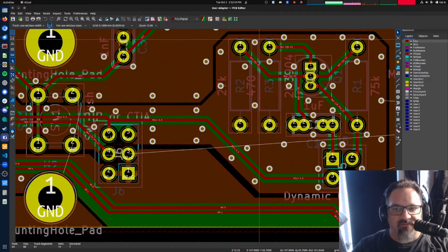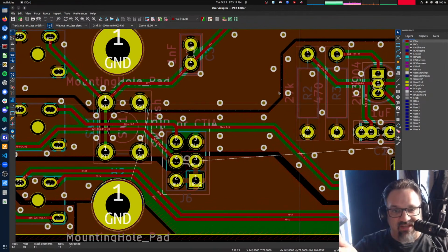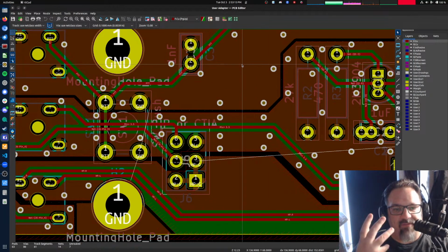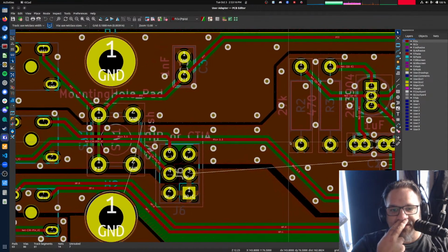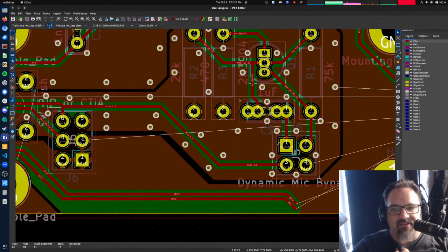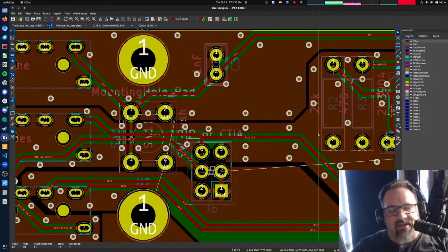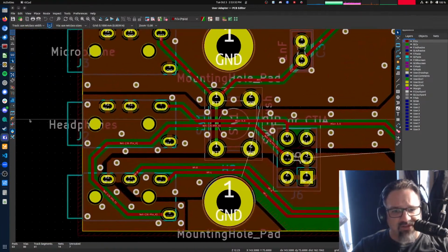So all of this here is mic ground or mic minus. I guess those are the only two places that have it. But by making the ground pour around all of this circuit, it makes it all reference to that ground. It should be the same, voltage-wise, as this ground, but I like keeping the currents isolated so that the return current from the PTT isn't going underneath this circuit, because then any noise that gets picked up in the PTT circuit will show up in the ground here, and weird things happen. It's better to keep it isolated for as long as you can, as much as you can.